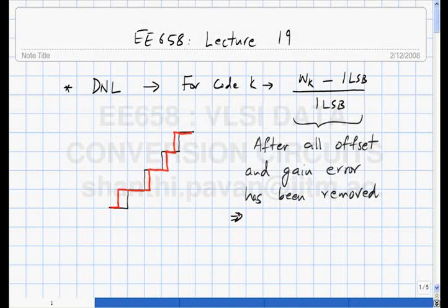The basic idea is to make a measurement on the A to D converter. You will get a plot of x versus y, some kind of staircase. The steps of the staircase will not all be of the same width. Some will be wider than others. If the converter is bad, then some steps won't be there at all. You have to jump twice as much to go up.